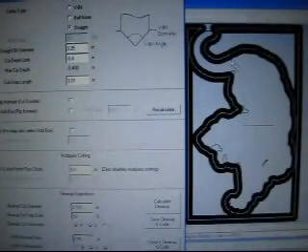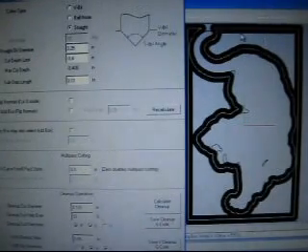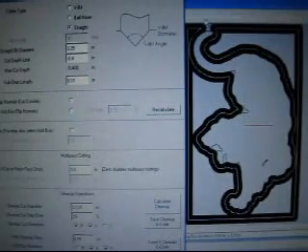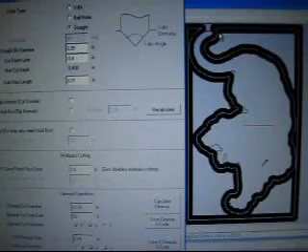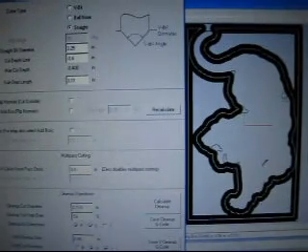This basically drew an outline around our part, which is what we want, because we want to carve away all of this other stuff around the tiger. That'll be our first machining operation. I can notice right away we're not getting into this section over here by the tail. It's not machining that area because the outline around the tiger is too small, so we have to enlarge that.